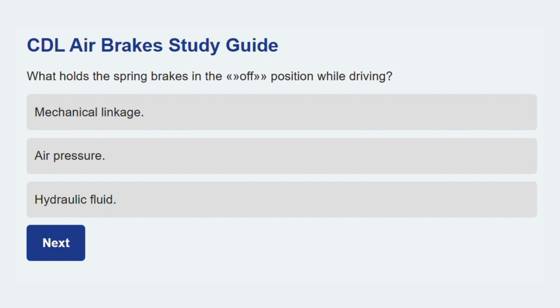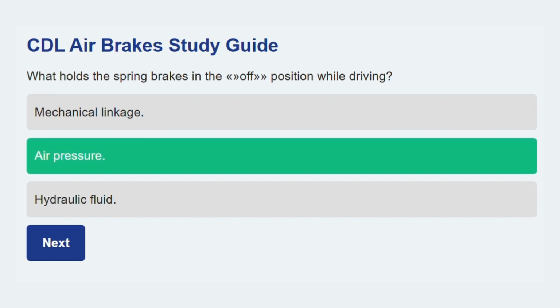Let's move on. What holds the spring brakes in the off position while driving? Air pressure. Spring brakes are designed to engage automatically when air pressure is lost, so air pressure keeps them disengaged.